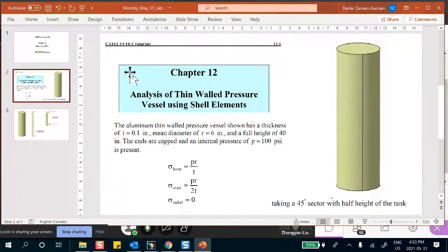In this particular problem, we have a pressure of 100 psi, a wall thickness of 1/10 of an inch, and a nominal radius of 6 inches. One thing about the wording, nominal dimension: if you see it on a test, it should not shock you.